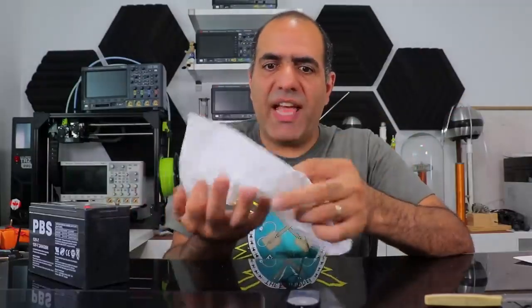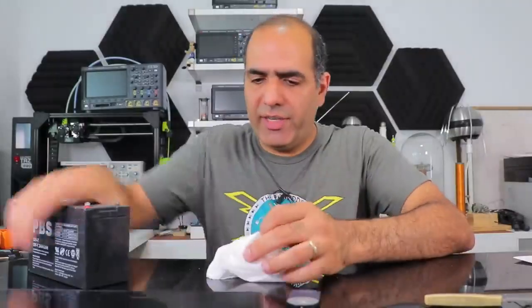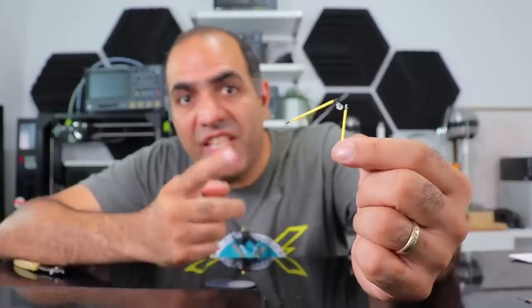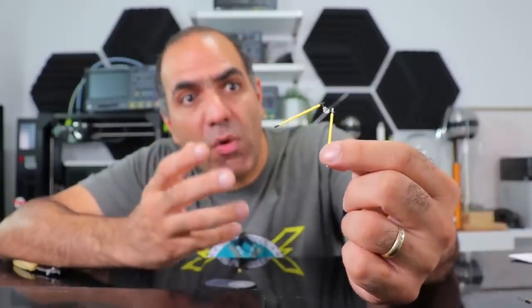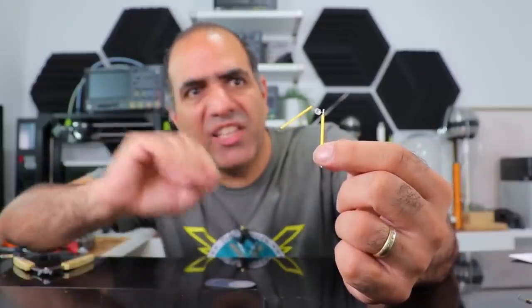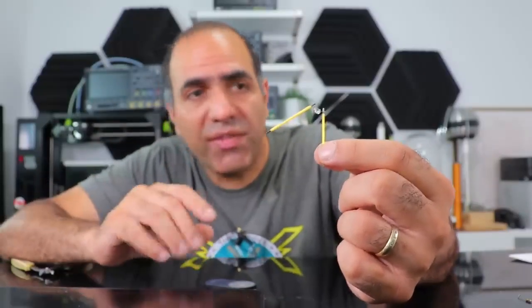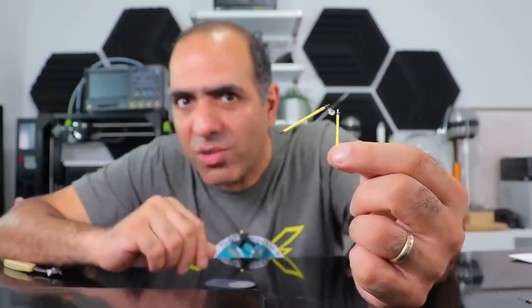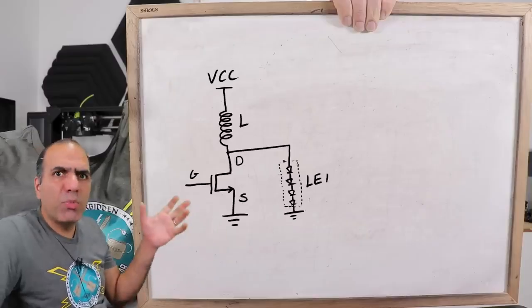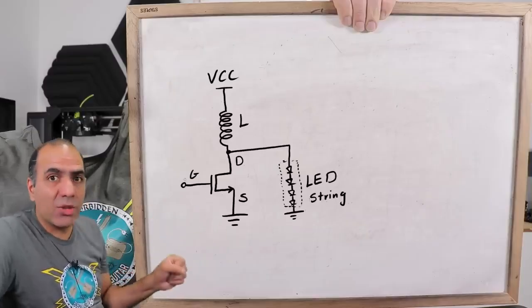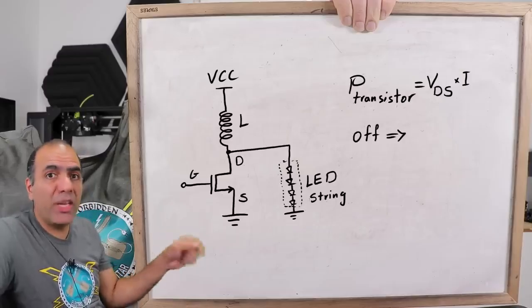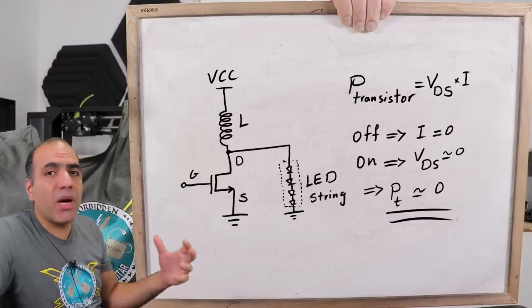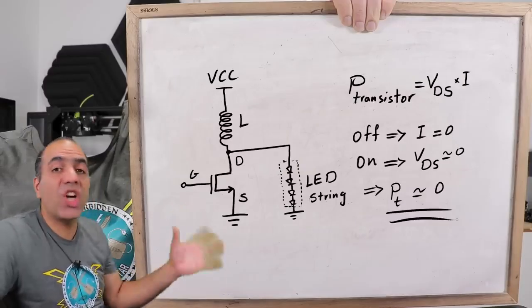Let me harvest another LED string first. These LED strings require tens of volts to turn on because there are so many LEDs in series in them. But let's see if we can turn it on using 5 volts. Here is a simple voltage boost circuit with a MOSFET transistor as the switch. The switch being fully on or off minimizes the power consumption over the driving circuits.